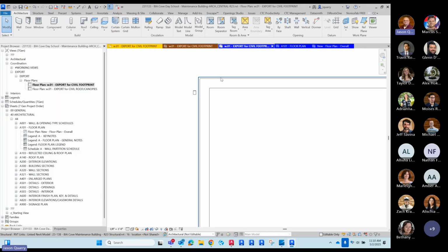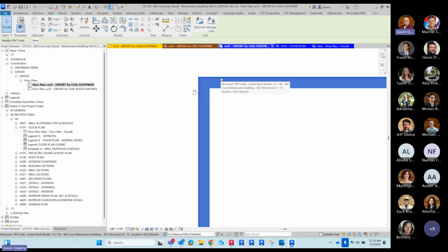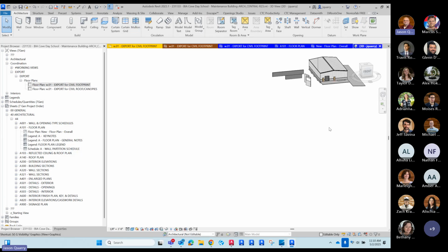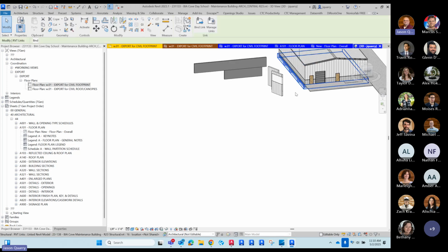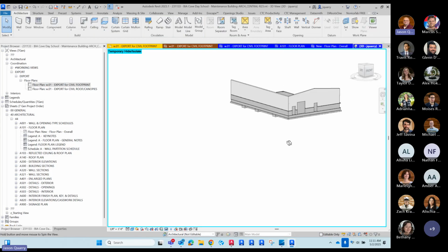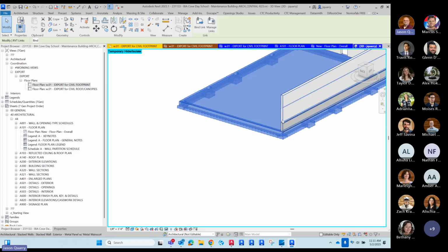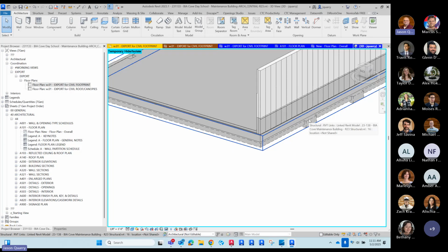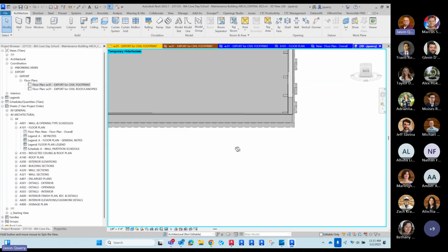For one, there is a structural Revit model, which is great. So ultimately, you hope and assume that this is accurate, right? If we look at this in 3D, let's isolate the structural model for a minute, along with maybe a couple of these walls, and maybe this will help show what I'm trying to show. This guy here is just the structural stuff coming from the structural model. Well, the footprint isn't technically the footing, because the footing sits outside of the foundation wall, right?